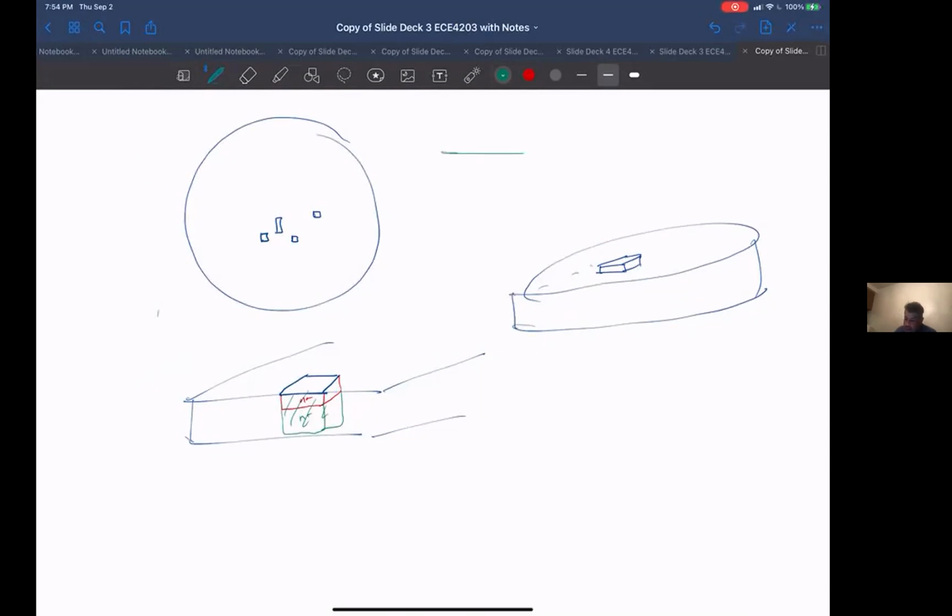For example, you might want to have N plus and then P plus wherever there is no N plus. So here you could use the same mask, but different photoresist. Some photoresists harden where there is light and some harden when there is no light. They're called light field and dark field photoresists.